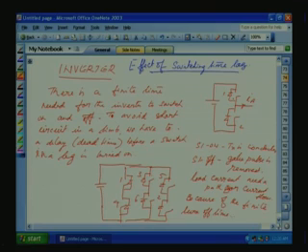Now, S1 is off. Now we are giving a switching lag time. S2 is turned on after some time. But in this case, because the current is negative, when S2 is turned on, the transistor is not conducting; the diode D2 will be conducting. Here it is D1.